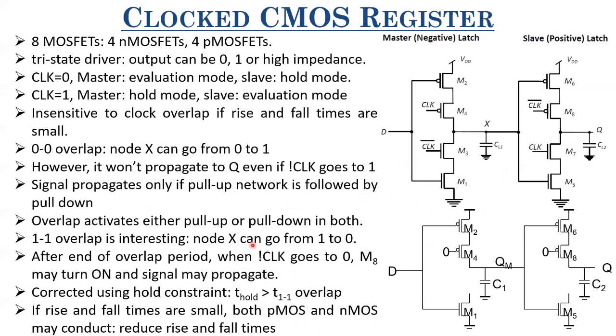Also, if rise and fall times are not small, if they are large, then both PMOS and NMOS may conduct, leading to short circuit leakage. You may have the problem of short circuit leakage.